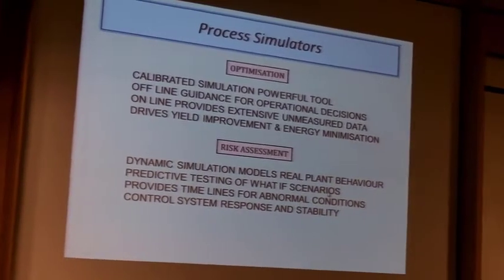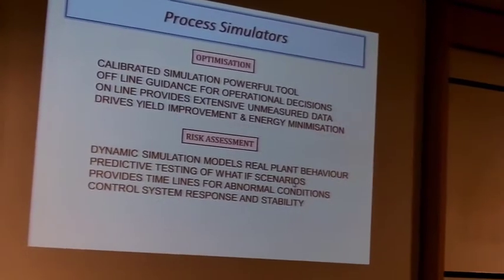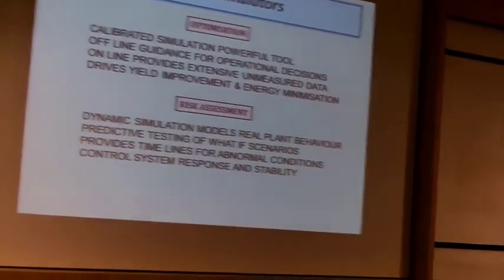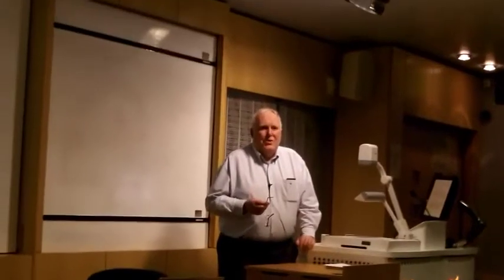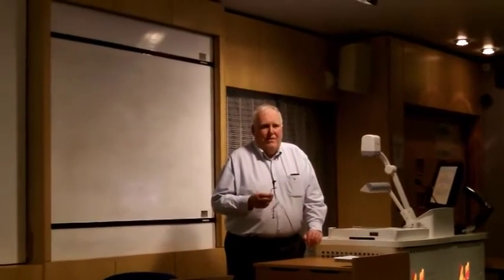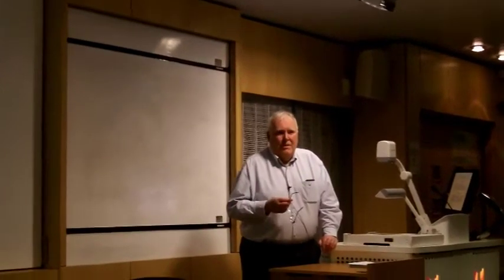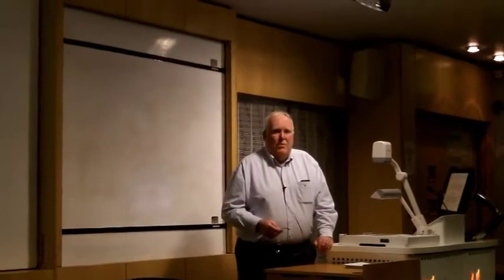Well, when you're coming up with things like relief valve sizing, presumably it requires a lot of confidence. How is that confidence validated? Well, that's why I said at the end, I wouldn't necessarily size it to the 6 things. I would say it depends on the process. As you probably are well aware, if you oversize your relief valve, that can cause you serious problems as well, because you can lift trays, you can create a massive problem on the column.